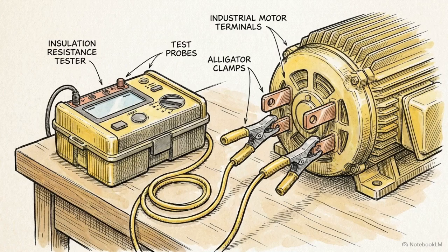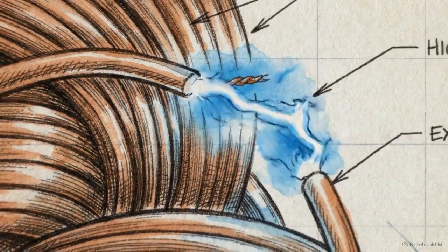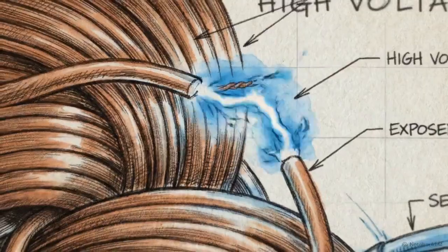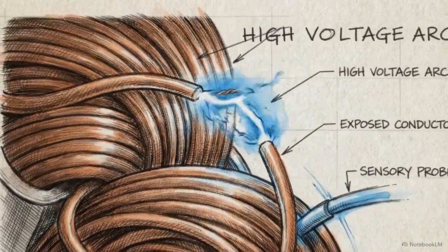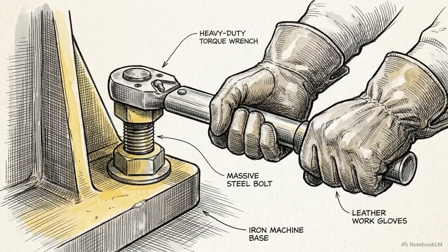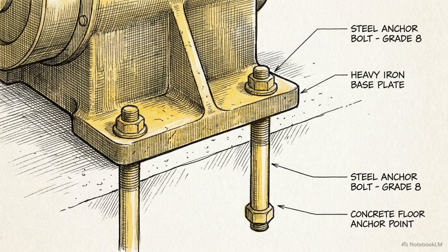The ad refers to Megger time. A Megger is an insulation resistance tester, used to ensure these high-voltage motors are safe. By pushing current through the motor windings, the electrician checks for degraded insulation that could lead to a short circuit. Hands-on fitting is necessary to physically mount and align this heavy machinery. Before any automation can occur, the hardware must be secured and calibrated.